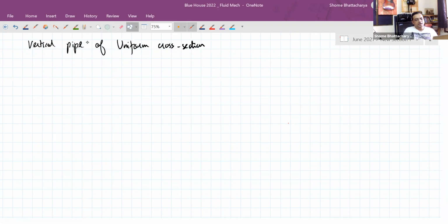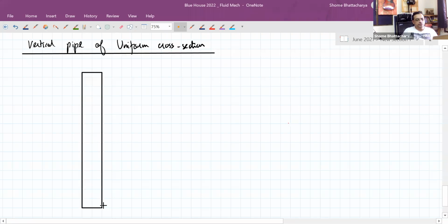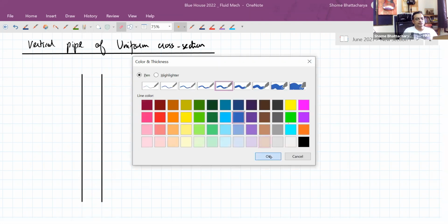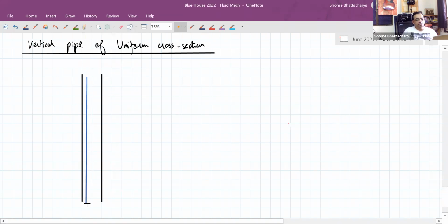Now, sometimes our natural way of thinking is that whenever there is motion in a vertical direction without any additional external force, there should be acceleration due to gravity. But here you have to understand it is not motion of an independent object through gravity. It is motion of a continuation of particles, which are the fluid particles, which are all interacting with each other through pressure. So when you consider a volume element of fluid, which is in flow through this vertical pipe, it's not like that volume element is having zero net force acting on it other than gravity, because it's not like an object in free fall. That volume element is being influenced by the pressure at its various surfaces.